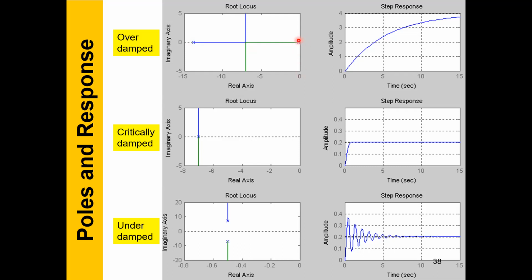Whenever you get near to zero, it means no movement, right? A very, very slow system. So just by looking at a pole very close to zero, it means it doesn't move. No action, no response, a highly damped system. Then in the critically damped case, you have both poles working together and you are not close to zero, which means you have some good action. Oscillatory poles means a complex conjugate pair of poles. The first time you see they are off the horizontal line, the real line, up and down, then you see the oscillations.